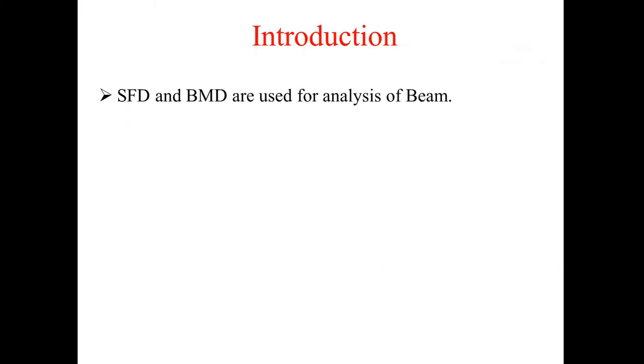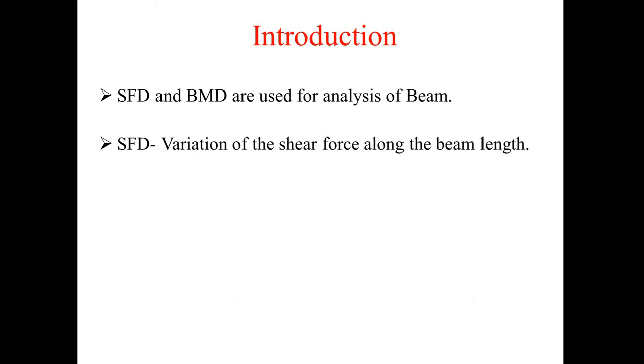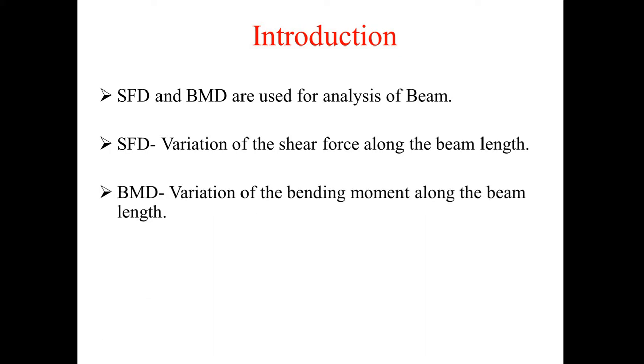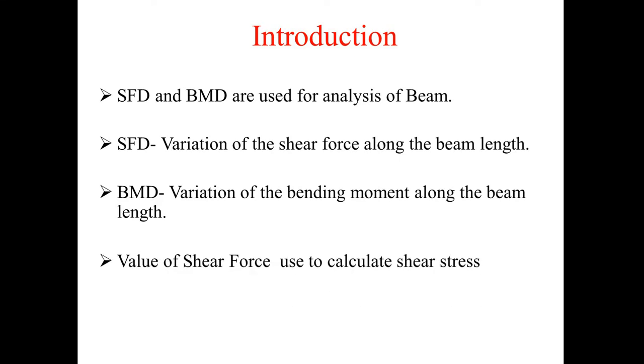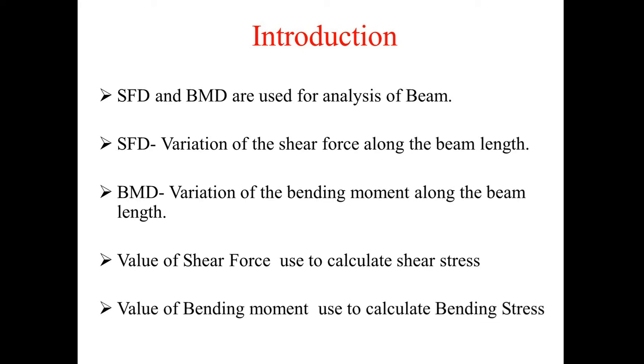So, start with the introduction. SFD and BMD are used for the analysis of beams. SFD is basically the variation of shear force along the beam length. BMD is the variation of bending moment along the beam length. The value of shear force is used to calculate the shear stresses, and the value of bending moment is used to calculate the bending stresses.